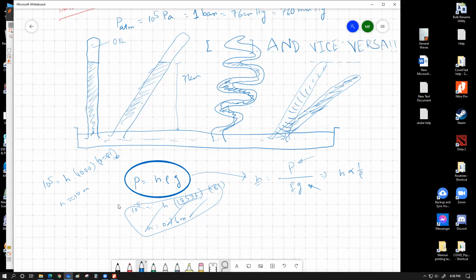So it is a clumsy process. That's the whole point of why we are so obsessed with mercury, because mercury has such a large density. It can produce a very high pressure at a smaller depth of itself, or under a certain small height. It can produce a pretty significantly strong amount of pressure. So the h can be pretty much manageable and small. That's why we prefer to use mercury over water. But if you ask me, well, what if we use water? Should we not call it a barometer? Of course, we can use any liquid. That's why for the first description of the barometer, up to a certain point, I have continuously used the term liquid.